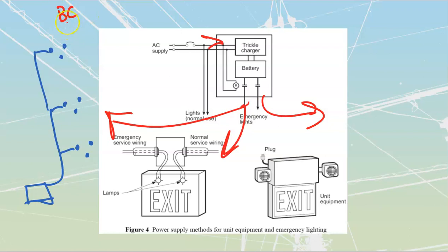Here's my BC Hydro. BC Hydro is going to go into the other side of all of these transfer switches. And then these transfer switches are all going to be automatically connected over to the BC Hydro side. And from there, they go out to their individual loads on each of these individual floors. So normally we see that we would be feeding in from BC Hydro through the transfer switch and over to our individual loads.